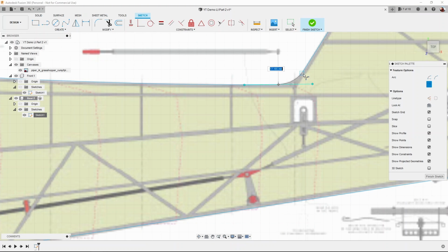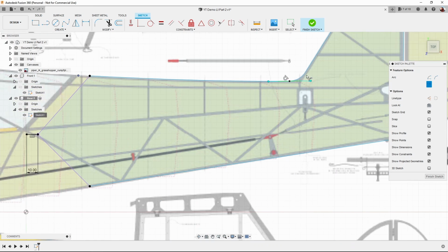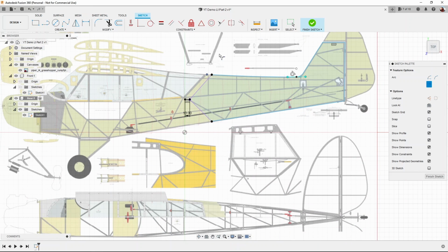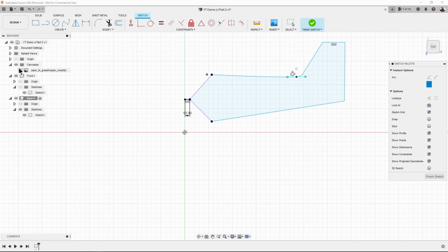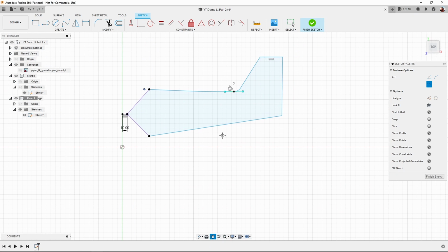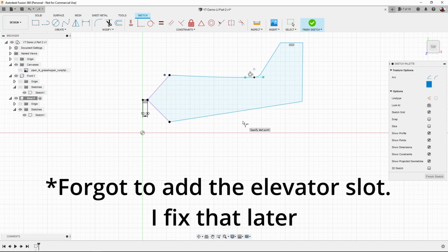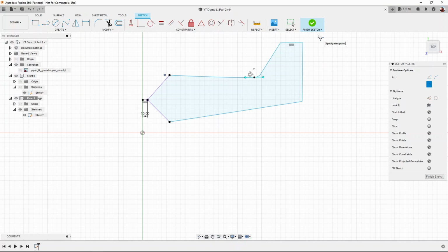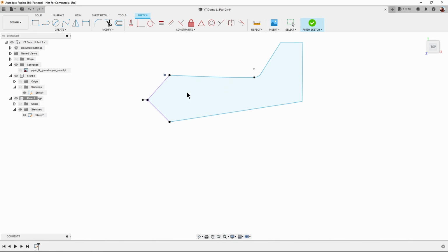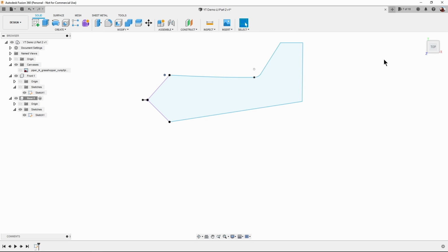So OK to that, and then we'll create an arc, a tangent arc. And we'll create it between them 2 points. And there you go, you can see it change colour then. So if we turn the canvas off, we've now got the rear section. So now we've got them sections, what we're going to do is we're going to extrude both of them. And this is what we need for making it in 2 parts when we're going to the manufacture section.